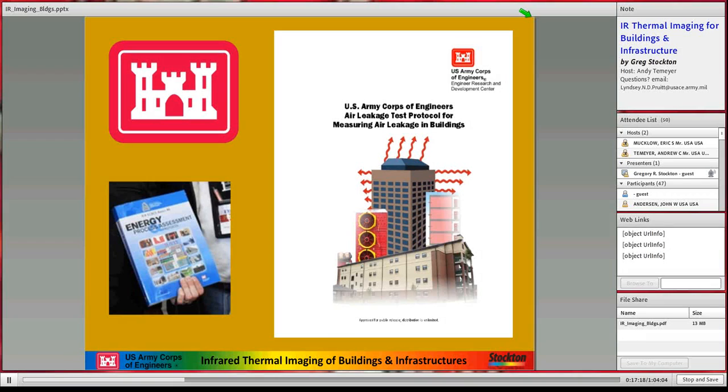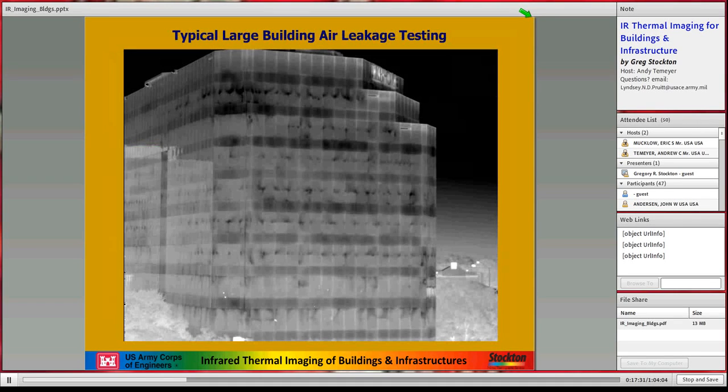Your payback in energy savings is measured in decades on buildings where you have to go in and do something, put 2 inches of insulation in a giant building. It's just not feasible. Replace all the windows. Replace all the window frames. Completely rebuild the HVAC system. It just doesn't have any good payback. So the idea is to commission a building once it's built. Commission it, make sure it's in good place, and then come back and retest it every so often.